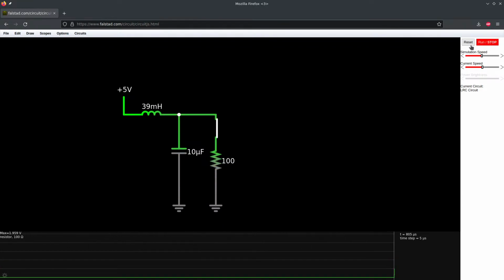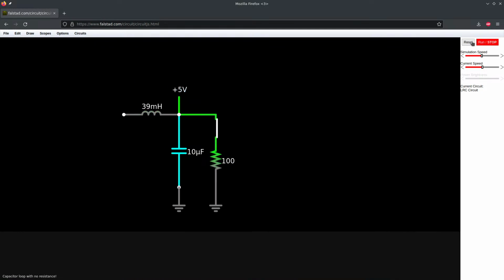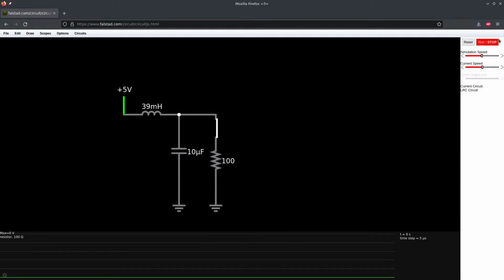So if I reset this, I'm going to charge my capacitor manually here in this simulation. So the capacitor charges up, right? And I need a resistor in here so this actually stops oscillating in this simulation. There's also resistance to it. So ignoring this current for the moment, the capacitor's charged up, so when you flick the switch, it actually draws current from the capacitor right away until the inductor is able to provide the current through the inductance. So that's why you have to have one there.